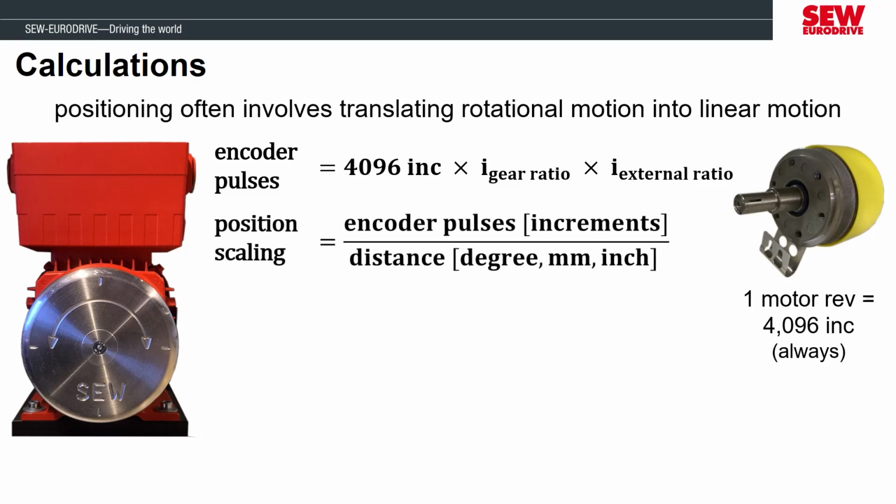Now that we know the total number of encoder counts to make a full rotation, we can introduce a new equation to represent a scaled position. So next, we need to determine the distance that is traveled if there is one full rotation at the driving wheel or the final gearbox. It will depend on the application, but there are numerous options for the type of measurement unit that we could use. I will mention that the scaling should be as precise as possible, otherwise it could cause issues.